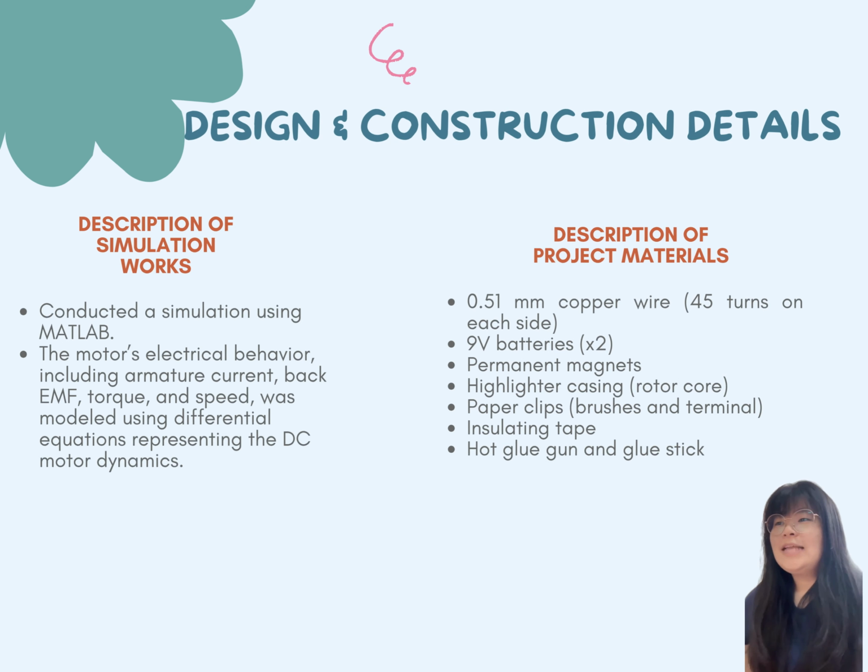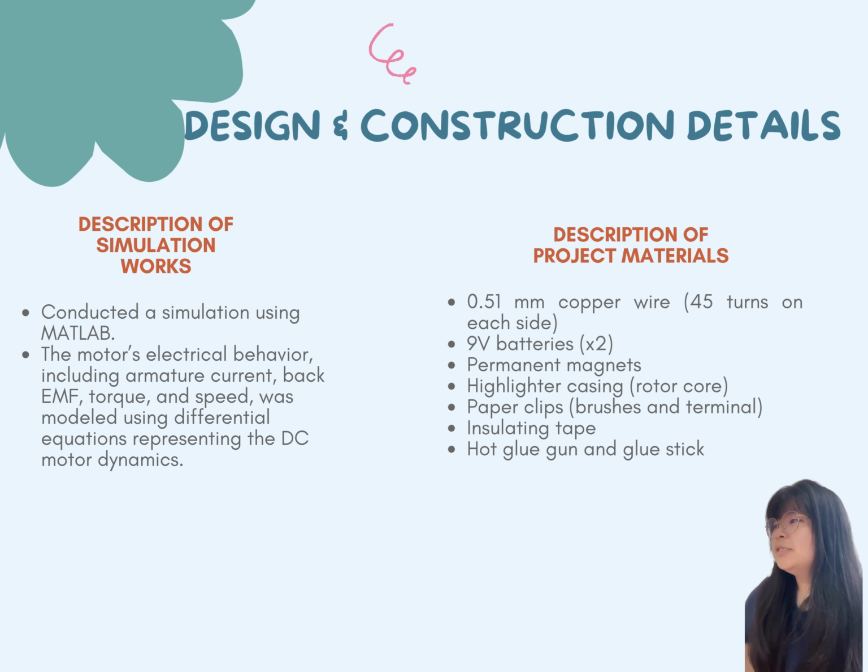Good day, Dr. Awan. I'm Ding Xin Yi. Today I would like to present the design and construction details. For the description of simulation works, we conducted a simulation using MATLAB. The motor's electrical behavior, including the armature current, back EMF, torque, and speed, was modeled using differential equations representing the DC motor's dynamics.